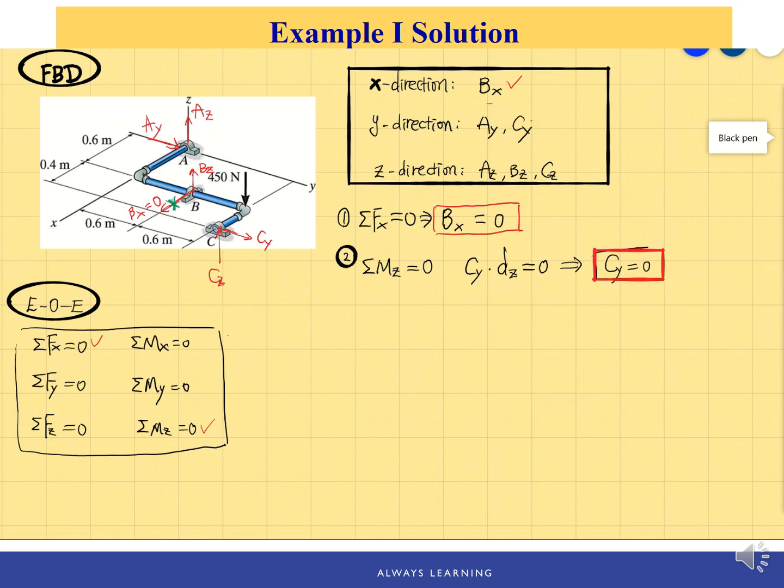Okay, so we check Cy, which we already know, put Cy equal to 0 on the free body diagram and cross this one out, and then it will not affect our other equilibrium equations because it's a 0 value. And for the rest of the equations, we probably just need to use them in order now, since I don't see anything too special for now.